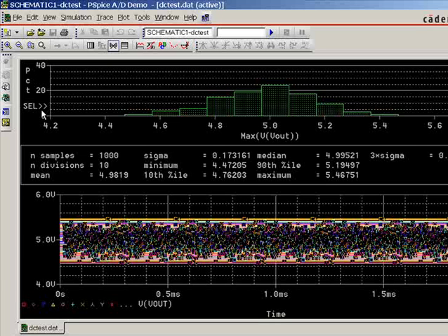In this case, we've effectively proven with a 17% variation in sigma to the input voltage, or to the main target voltage, that the constant current bias is far too well spread. This is a very wide curve. We would want a much tighter curve, which would effectively represent the fact that the circuit is immune to variations in component value. For example, the potentiometer bias.